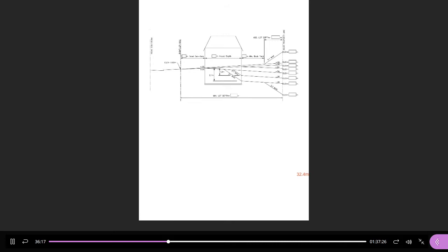Then you can't build a house right at the street line. So you have to have what's called a front setback. So the front setback is typically, there's a range, but what I want you to use is going to be right here. I want you to use 8 meters. Okay. Sorry, 32.7, my mistake. I said one thing and my typing did something else. Sorry. Thanks, Sumitra. So it's 32.7 meters deep. The front setback to the building is 8 meters.